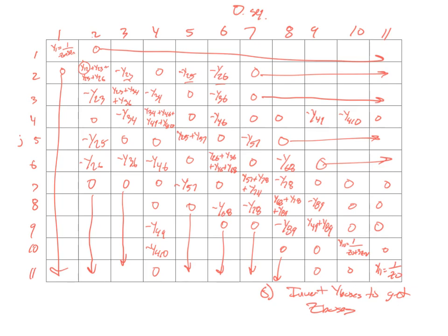So you're going to have to invert an 11 by 11 matrix, which may or may not be a trivial amount of work. It's something to consider. Now that we have those, we have enough information to start actually calculating fault currents once we actually build our diagrams. So we're going to look at the 3 different fault types. We'll start off with a single line to ground fault.